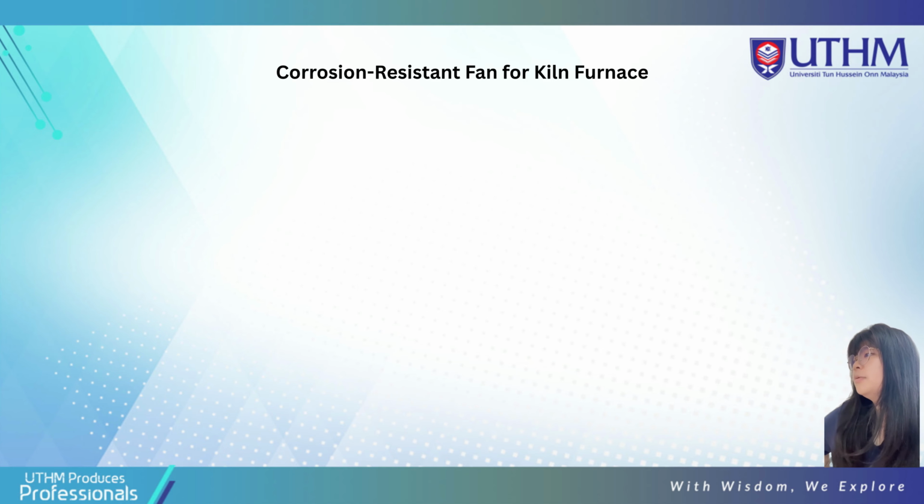So the third problem is motor overheating. It may possibly be caused by blocked airflow and excessive load due to dust flakes. So we need to install thermal protection by using thermal overload relays, and we need to do regular cleaning by cleaning the air intakes and fans.